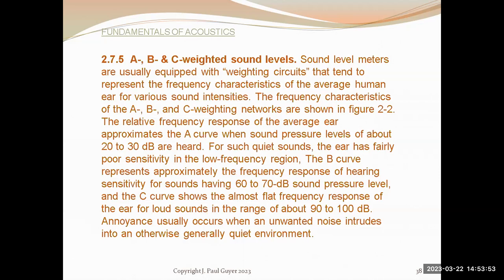And you need to have this fast slow knob because if you sample the sound with a high level of frequency, like once every 1/100th of a second, the needle on the sound level meter will be bouncing back and forth like crazy, and you won't be able to read the sound level meter.